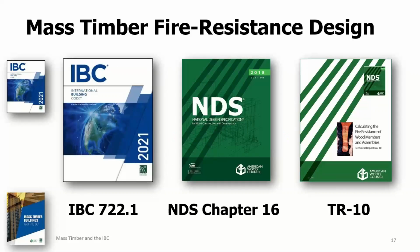IBC section 722.1 references chapter 16 of the NDS, the National Design Specification for Wood Construction. And that's for calculating the fire resistance rating of exposed wood members and wood decking. And then AWC's Technical Report 10, which I'll call TR10 from now on, provides background and examples on performing the actual calculations that are specified within Chapter 16 of the NDS.